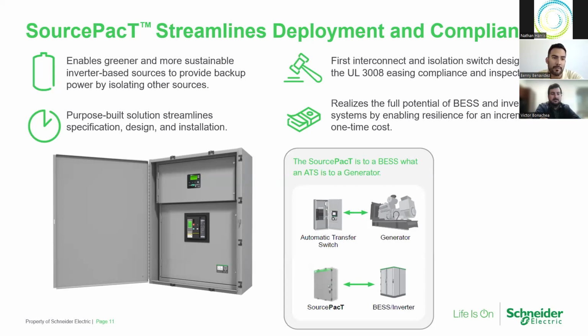How this differs from most microgrid solutions when you're thinking about designing for resiliency: at some level, most microgrid systems require some type of microgrid controller. That could be a very basic microgrid controller with IO contacts that communicate to an energy management system, or a sophisticated microgrid PLC controller that's activating several use cases in the energy storage system.